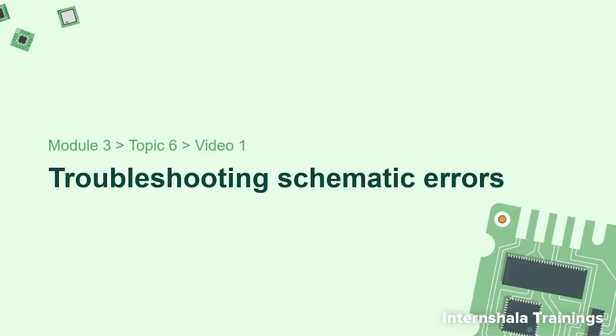This is actually a very important point. If we try to create the layout without resolving the errors, then there will be a lot of issues in the layout design, and those issues may reflect in the final manufactured PCB. That's the reason we should always resolve the errors in the schematic design first, and later we should start with the layout design. All right, so now let's start with the final video of the final topic of this module.